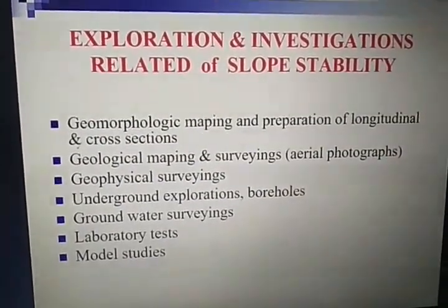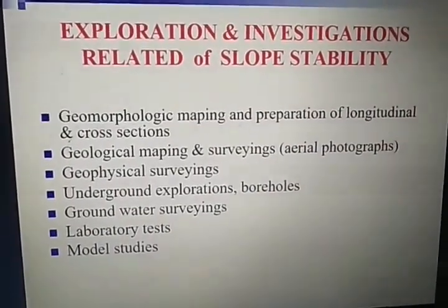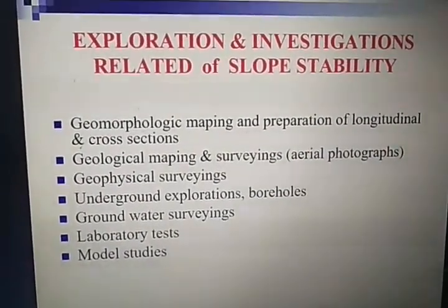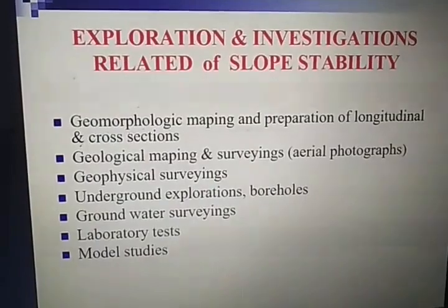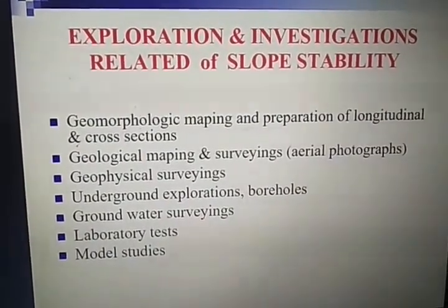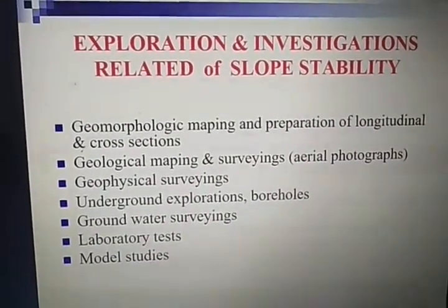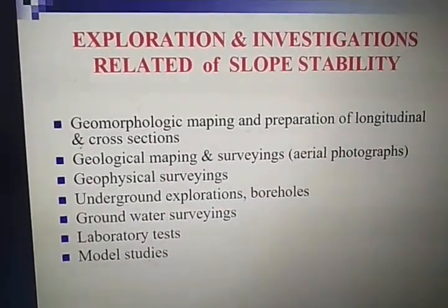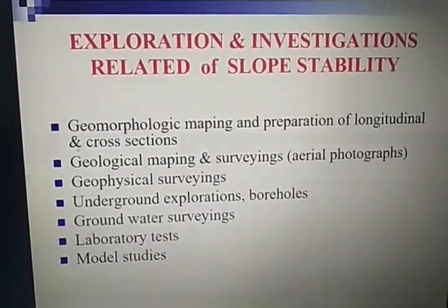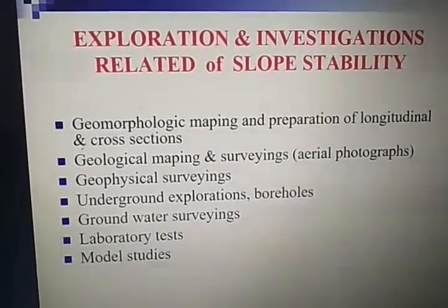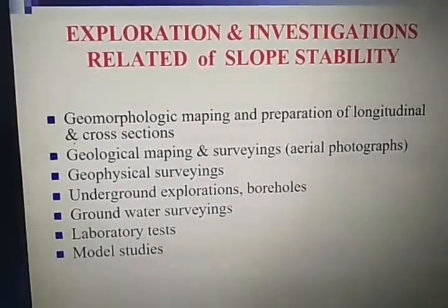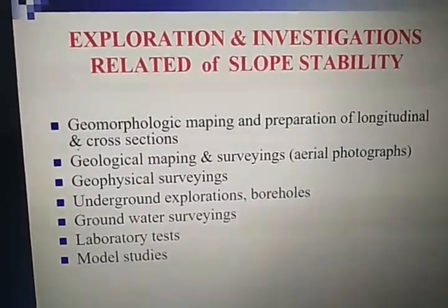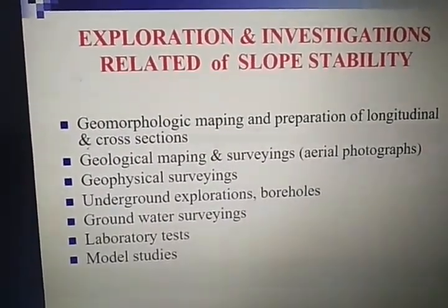Explorations and investigations related to slope stability. Geomorphological mapping and preparation of longitudinal and cross sections. Geological mapping and surveying, geophysical surveying, underground explorations, groundwater surveying, and laboratory tests and model studies. These are to be studied before you go towards the tunnel excavation.